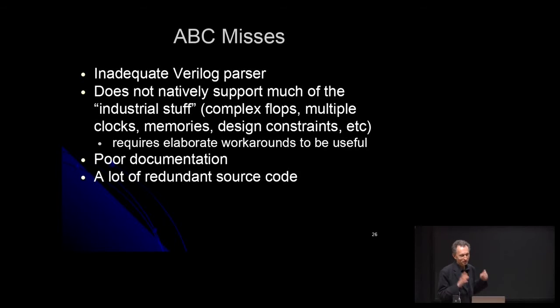And when it comes to ABC limitations, it doesn't have its own Verilog parser, but fortunately we can use Yosys as a parser. As I mentioned, ABC is integrated into Yosys, but independently I integrated Yosys into ABC. So when I'm running ABC, I can actually use Yosys to read in any design, and I continue working on it in ABC. So both projects benefit from each other a lot.